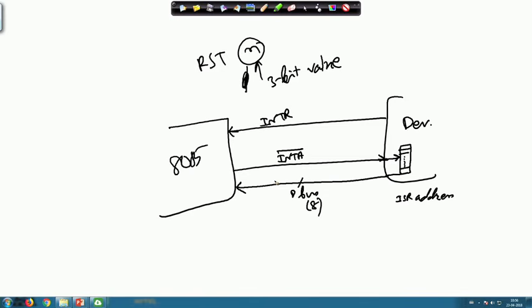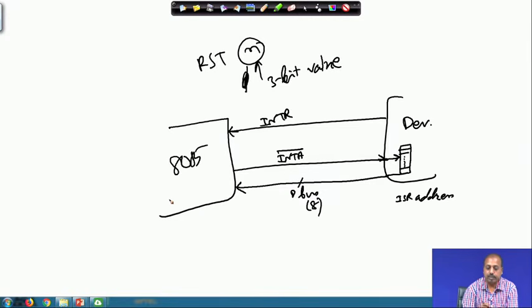On the data bus, it will expect that one of the RST instruction codes will be put here, and the 8085 processor will then execute the RST instruction. This RST instruction transfers the control to some location, depending upon the value of n. It will jump to a predefined, pre-specified location, and from that point onward the processor will start executing. So it is expected that the interrupt service routine for this device is located from that particular address. This way this can be a non-vectored interrupt.